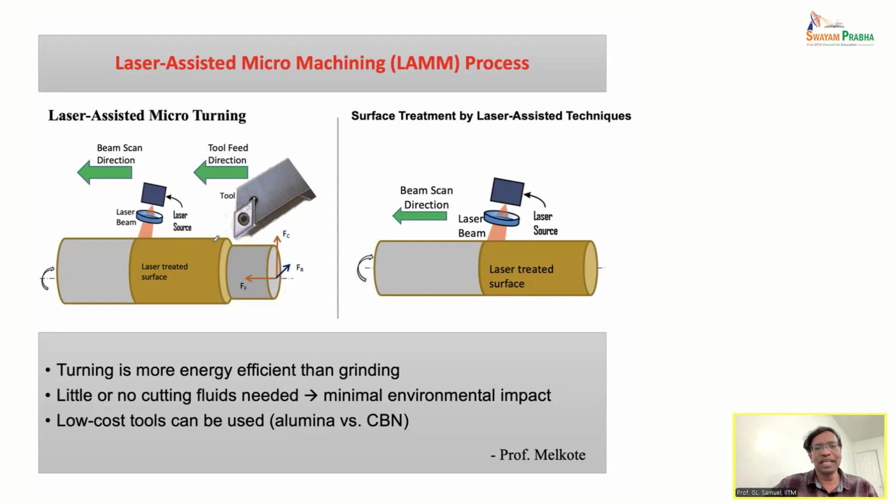That is more efficient than cutting the hard material. Thus we get much better surface finish, the cutting forces are less, and we can increase the tool life.